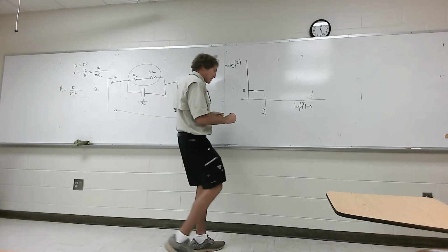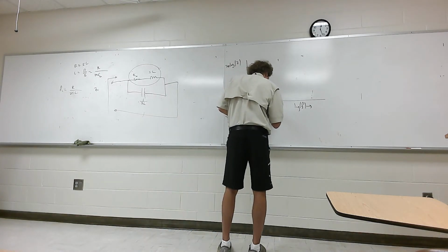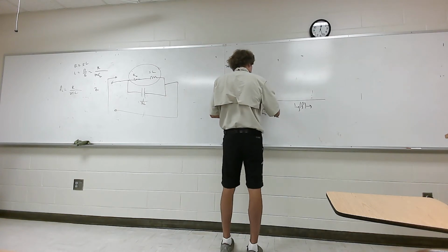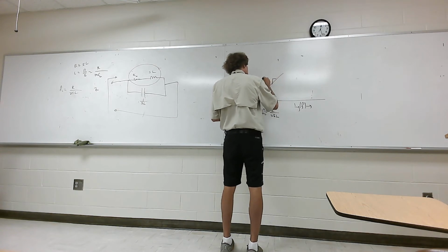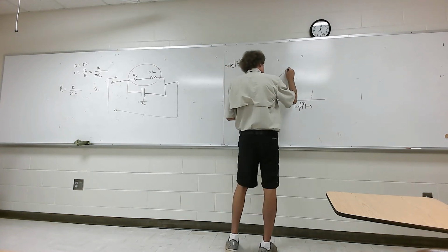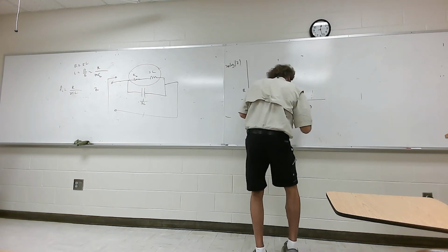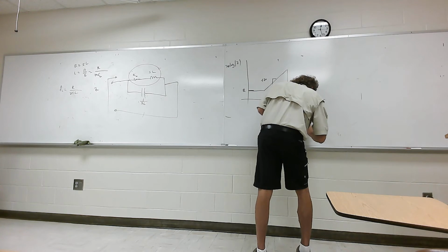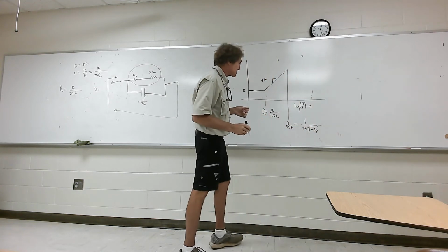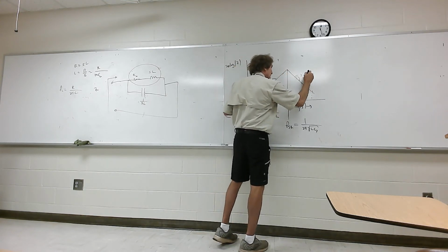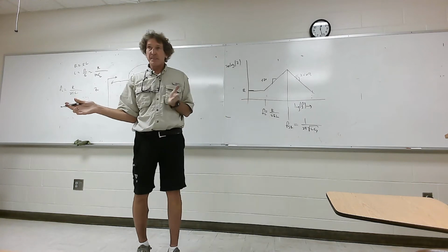So this is, and then it's going to start going up at plus 20 dB per decade, until it hits the self-resonance frequency here. And the self-resonance will be 1 over square root of LC. And of course, that's the parasitic capacitance. After it hits self-resonance, it's going to come down at minus 20 dB per decade. And that's the way an inductor looks, period.